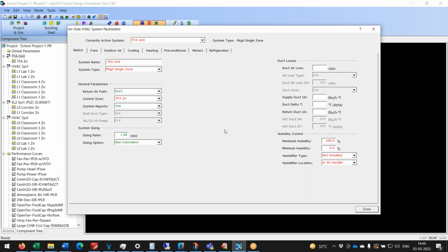You just get the tonnage then. What about the compressor COP? COP is this one, the condenser TR that we are measuring now. So we will divide the cooling watts. That TR will be multiplied by 3.51, and we will get the cooling watts, which is then divided by the electrical input. In the case of small ACs, it will be measuring the energy efficiency ratio, EER, and in the case of larger systems, it is COP.